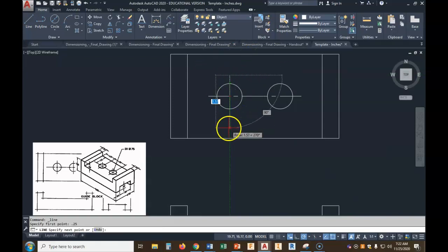Now I'm going to drag down, and like I said, I know this line's going to end up being 1 1/4 inches long, okay? Now the other way of doing that, let me get rid of it. The other way of doing that is I can start here and drag down. This is the old-fashioned way, and I've done this a lot. Drag this point down now 1/4, drag this point up 1/4. Yes, that keeps you from doing your math, okay?